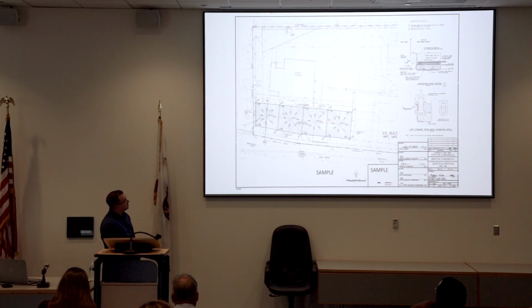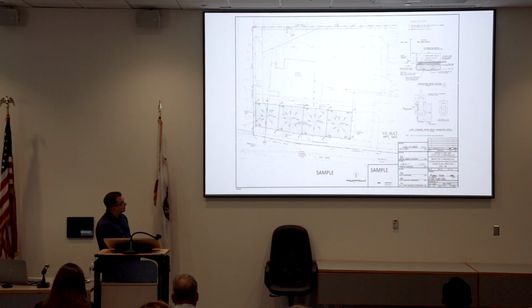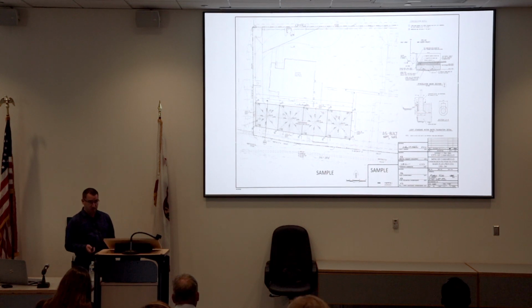So you can see the detail of the actual underneath filtration, but here's the swale itself, and what you're not seeing is the pipe that takes it down into that area. And then there's a bunch of rock down there with roughly 40% void volume, which is able to capture and retain that water and then let it infiltrate into the ground.